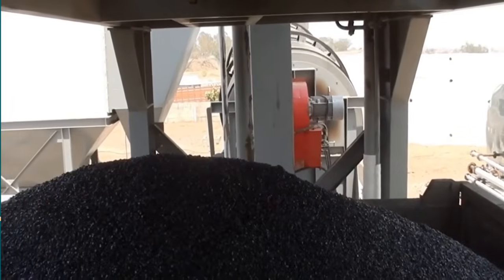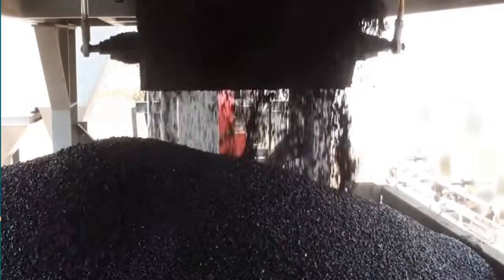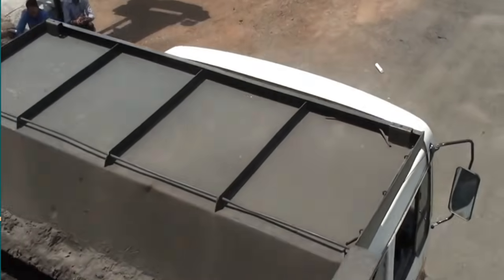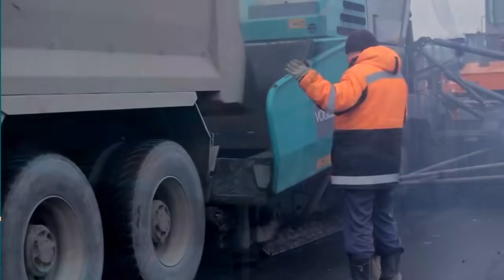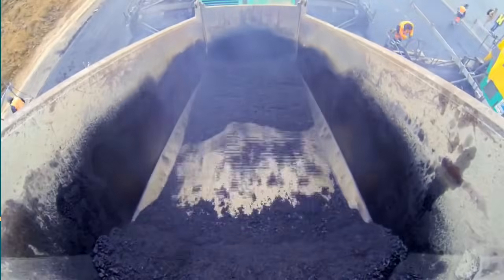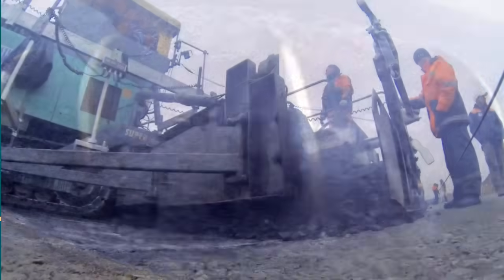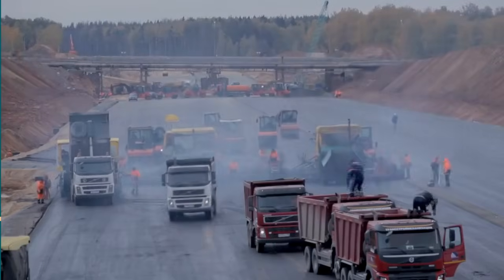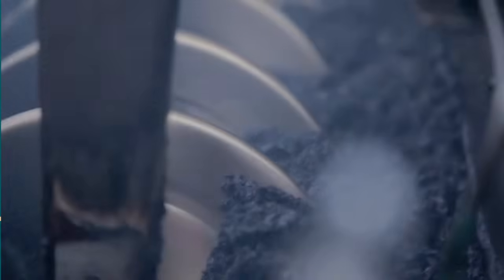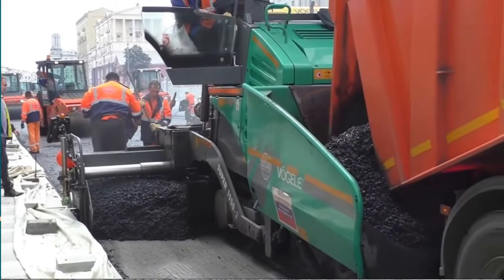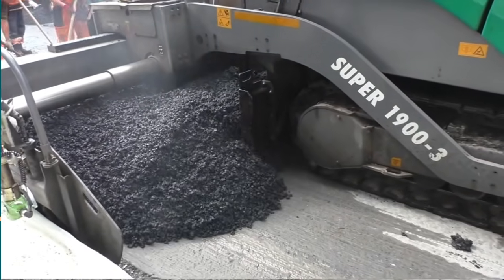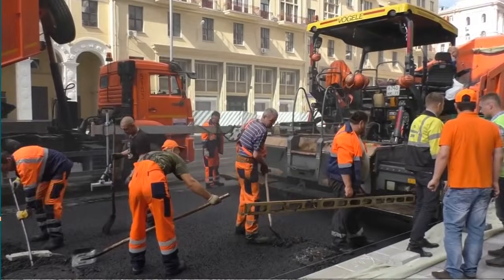If required, cover with tarpaulin to maintain the temperature and to control the dust. Spreading or laying: the mix shall be slowly discharged in the paver hopper, while both the tipper and paver move forward steadily and slowly. If possible, the paving shall be done in one go for the full width of the road. The normal temperature of the mix at the time of laying shall be 140 to 160 degrees Celsius. However, it shall not be less than 120 degrees Celsius.